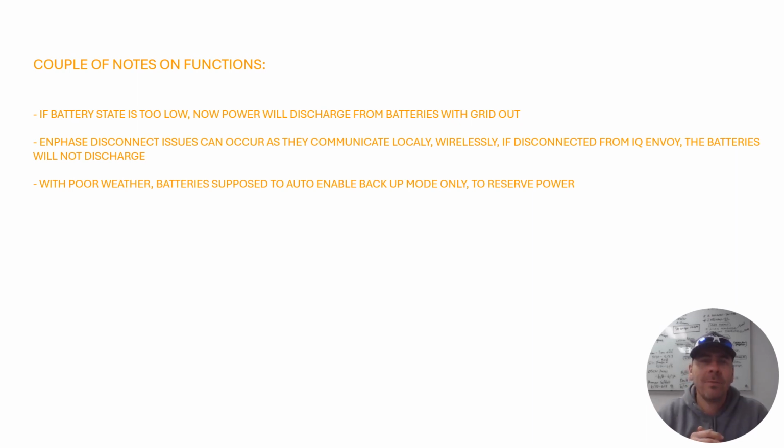I know Enphase has some difficulties with the Zigbee or Bluetooth communication they use between devices. Sometimes you'll see on monitoring where it disconnects, and unfortunately, until that communication is reestablished, the batteries aren't charging or discharging. It doesn't happen that often. I have seen it a little bit more with Enphase than with other systems.